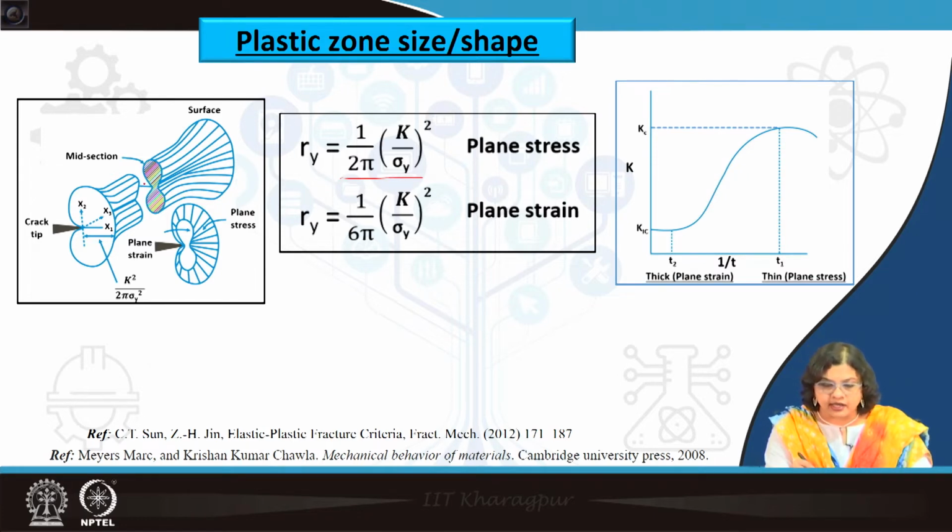On the other hand, at the interior part, particularly in the middle, the plane strain condition generates, which essentially means a triaxial condition of stress and biaxial strain. So, overall the strain generated is constrained, and the amount of strain is 1/3 of that generated under plane stress condition.